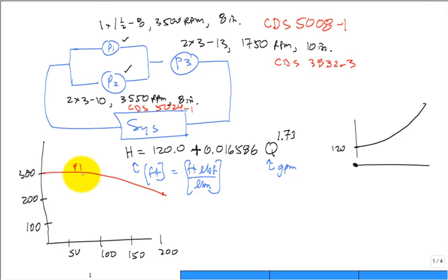Okay, now what about pump 2 curve? Well, it's an 8-inch, so it starts at just a little bit below. Let me change color on it, put it at this color. And if I look out, it goes out to 500 GPM. Hey, did we put this on a large enough scale? How come somebody told me to stop at 200? 200, 300, 400, 500 GPM. It should be out to like 550, 600, right?